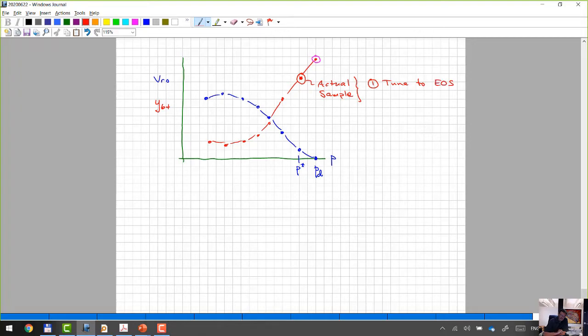Then you calculate, obviously, the dew point, which is equal to the lab data. It's matching the lab data. Now your sample that you actually have here, when you do the CCE or CVD of this test, will look something like this. It's going to have a dew point here, and then it's going to have liquid dropout that looks something like that, right? It's going to be leaner.